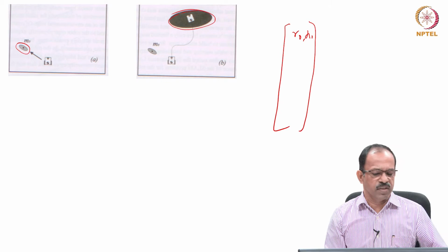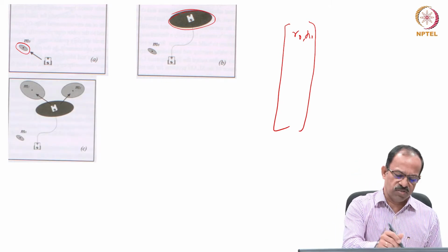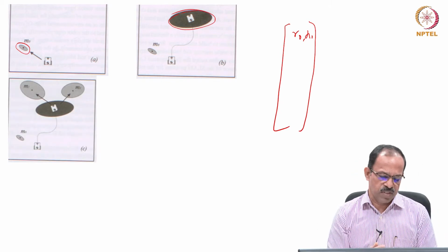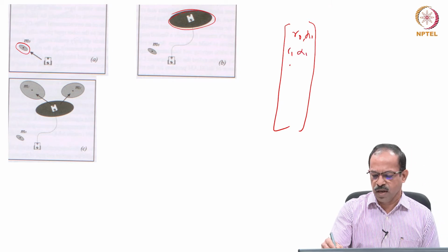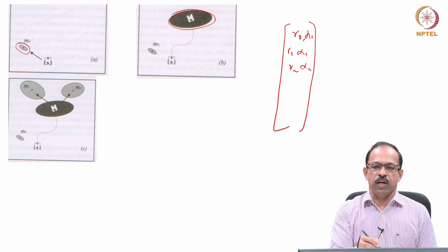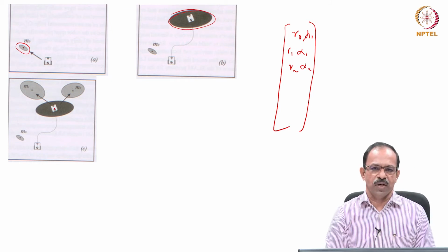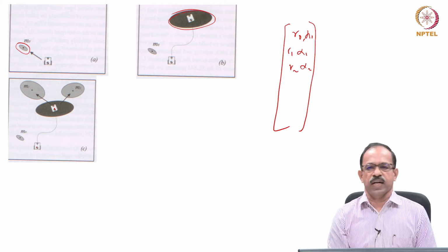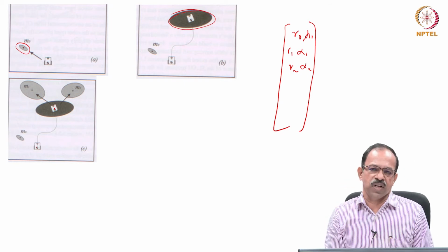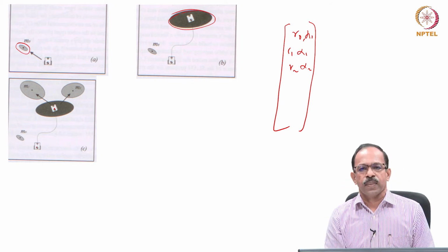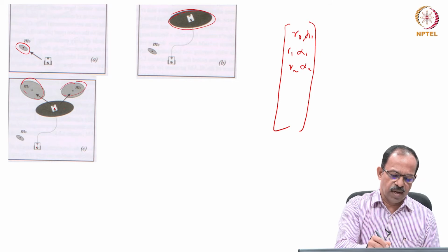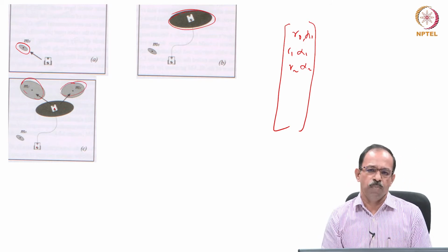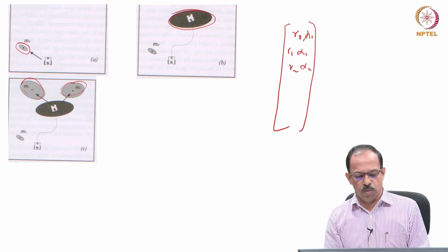And again, it will be seeing some objects. It will see two objects, or any number of objects, and record them as M1, M2. It will say, okay, I am seeing R1 alpha 1 and R2 alpha 2, from my current position. Based on the odometry, it calculated the current position, and from that position it is seeing two objects. It has uncertainty because the position is uncertain and the sensor uncertainty is there. Therefore, there will be large uncertainty in the position of the object also.